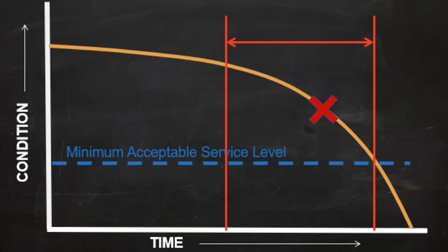And again, part of the reason you want to track this information is because, like everything else, how pipe or valves or other equipment deteriorates in your particular situation can be very different than it does someplace else. We've seen utilities where pipe on one side of town deteriorates at a much faster rate than the other side of town because it's got acidic soil and the metallic pipe just gets eaten up quicker. And that's the kind of thing that you want to be able to track and predict over time. So again, you can do that budgeting ahead of time, and you can do that planning.